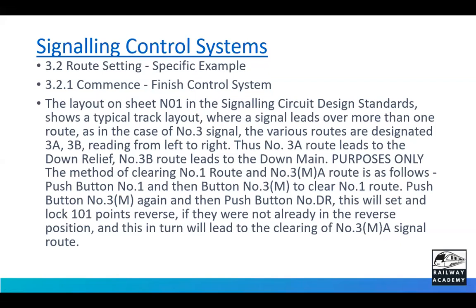So you have your route setting, how it has to be done. You have the entrance exit system and the one control system, different systems like that. One control system is an old system, still existing, and the new system is the entrance exit system. That is also there. All these things are explained. In a one control system, you individually operate the points and then finally operate the signal. In the NX system, you press the point button and press the route button. That is the main difference.